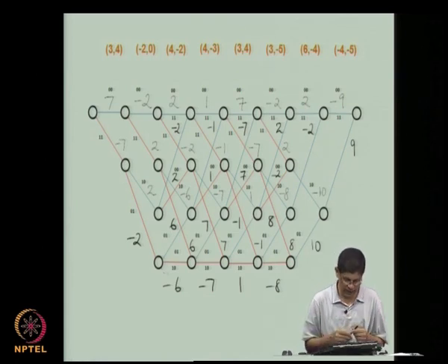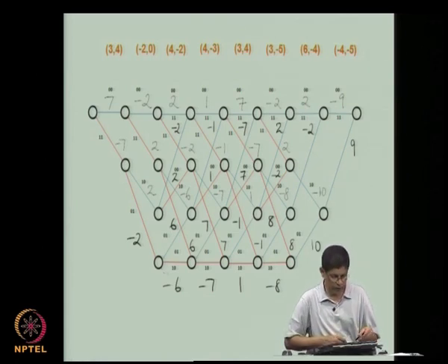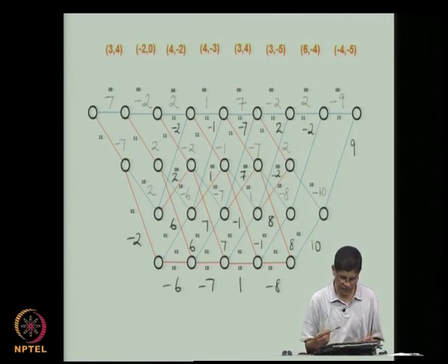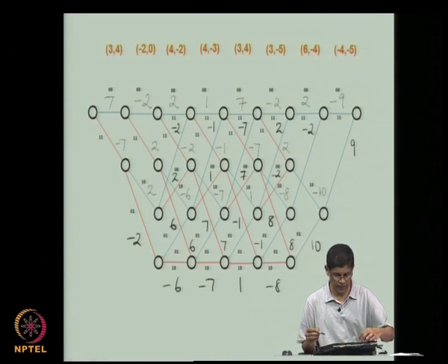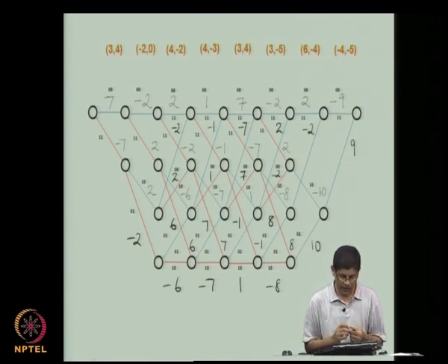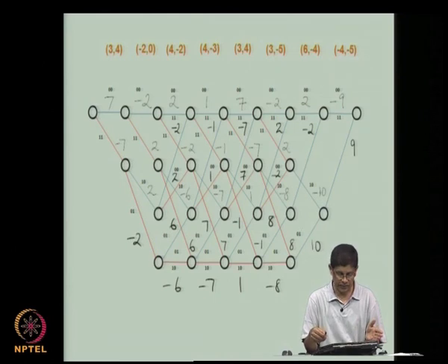Okay. So what you can actually do is you can keep track of metrics. This partial inner product is called the branch metric, and the total inner product is the code word metric, or a path metric. You can compute the path metric by adding the branch metrics.